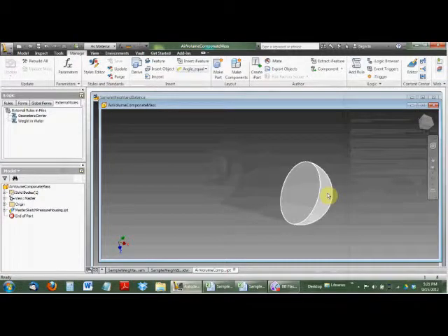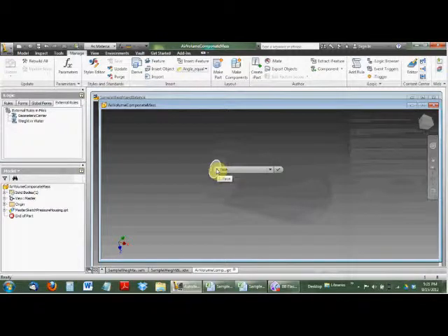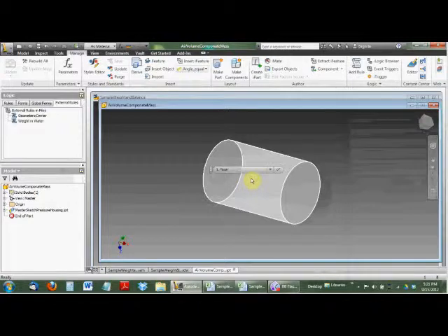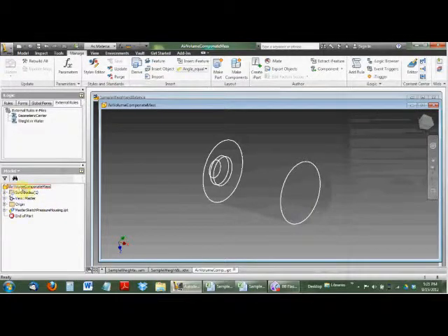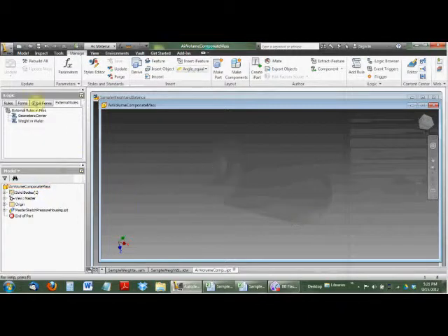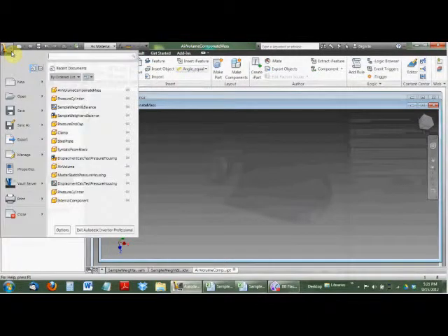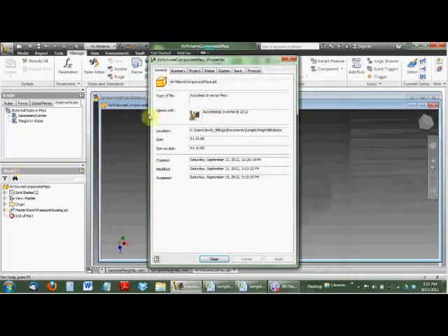Now I did one thing a little bit extra, right? So oftentimes when you're making larger complicated models, you don't want to put all the chassis components, the resistors, the circuit boards, whatever, inside a pressure housing that's a supported void. It's too much. You don't want that level of detail. And so how do you get around that? Well, in this case, you'll notice the name of my thing is air volume component mass, right? So Inventor allows you to fudge the iProperties, and that's what I did.